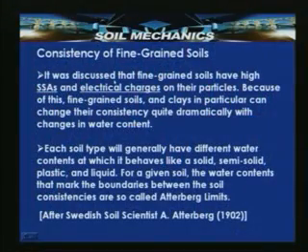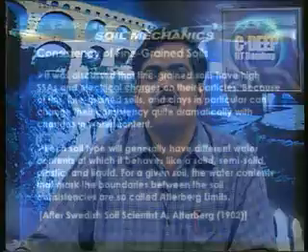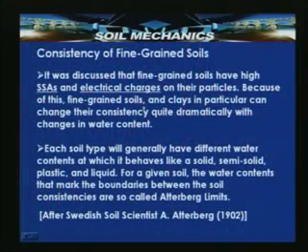As we have studied earlier, fine grained soils have higher specific surface areas, because the finer the particle size, the higher the specific surface area, and they have higher electrical charges around the surfaces of their particles. Because of this, fine grained soils, and clays in particular, can change their consistency quite dramatically with changes in water content. With the availability of water, the consistency can change from a firm to a soft state, or a very stiff to a soft state.